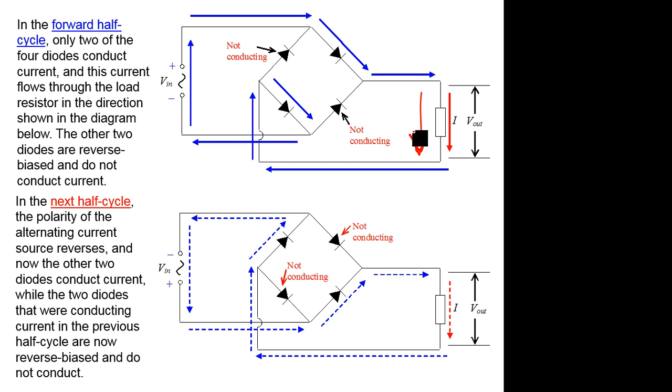Now you reverse the direction, same thing. Come down, come here. Cannot turn left, go right, come down. Go down again, okay. Very important, it goes down through the resistor. Come left, go up. Oh, can I go up? Yeah, I cannot go down because here is higher potential, so I must go up. Complete the circuit. But you realize in both situations, the current in the resistor is downwards.